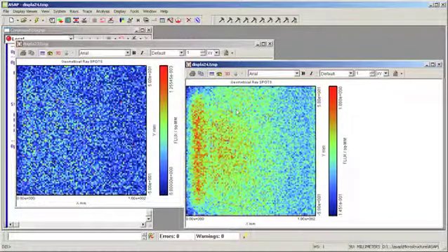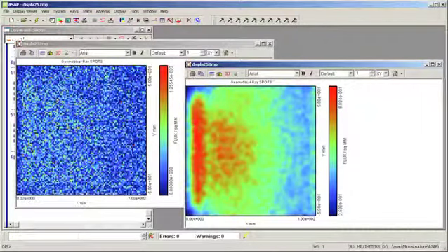We see that the distribution is much smoother, and we can see many more details, but we still have large statistical fluctuations. We can reduce this by either ray tracing even longer, or by doing some averaging, where we average each pixel with its neighbor. I'll do this twice. Now we have a relatively smooth distribution that shows us the characteristics of the irradiance on the display for the explicit model.